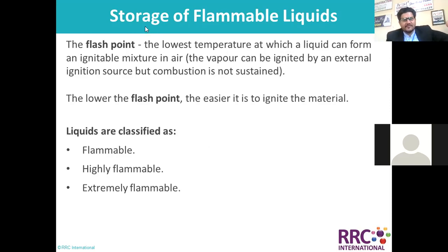Same, if your company has storage of flammable liquids, there is always a flash point, the lowest temperature at which a liquid can form an ignitable mixture in air. That means the vapor can be ignited by an external ignition source, but combustion is not sustained. So flash point is critical.